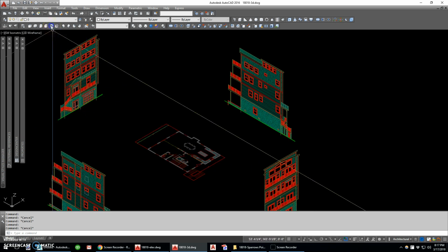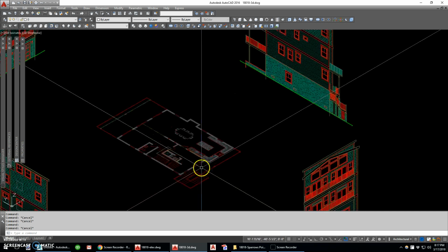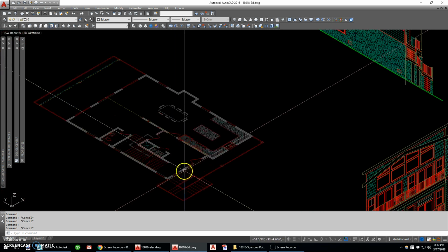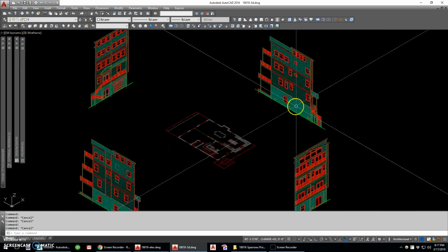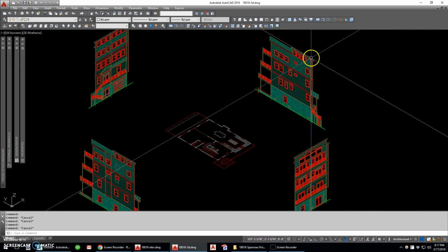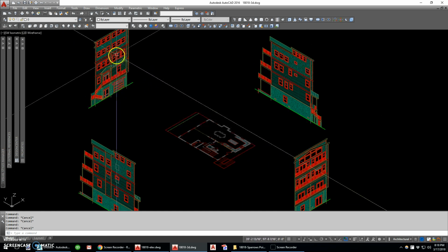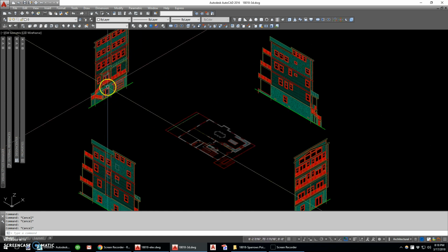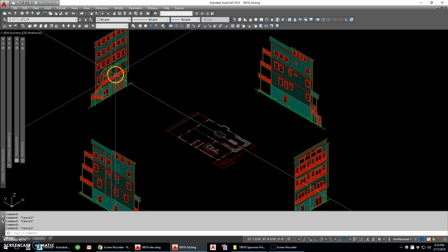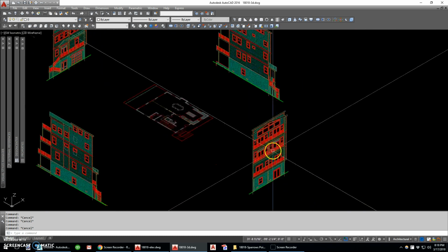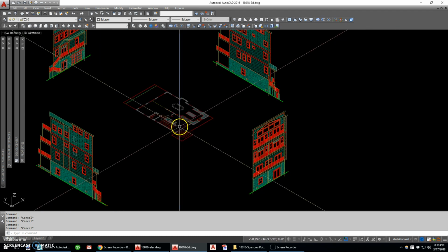So the first thing I'm going to do is look at the front view, because I'm going to start with the front of the house. And again, if we look at the plan here, we can see the front of this house kind of jogs. I look at the elevations, the front looks flat. There are no different jogs in the second, third floors. So this is one wall, and this is the other wall. Between those 2 walls and maybe the back of the house, I can get all the geometry I need to model this thing.